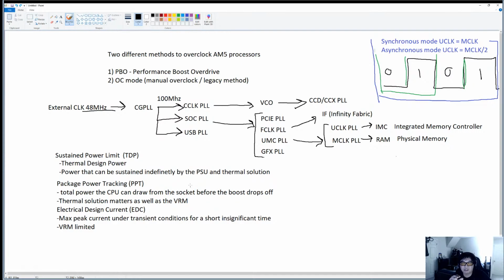By default, they all are essentially doing what Intel is also doing, where they're running these three parameters in unlimited power mode, because if you try to tune these, as soon as you go to custom or manual, you'll see that the limits they've set are so high that the processor will never use that much power.